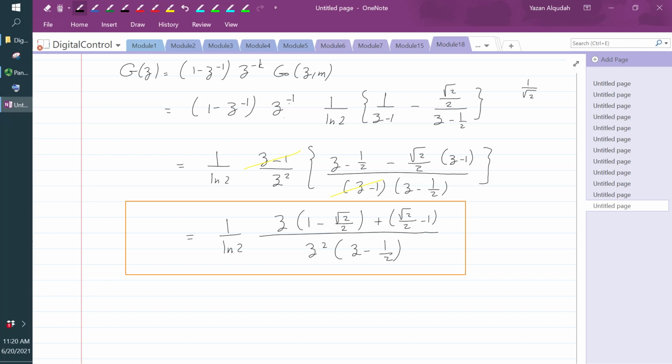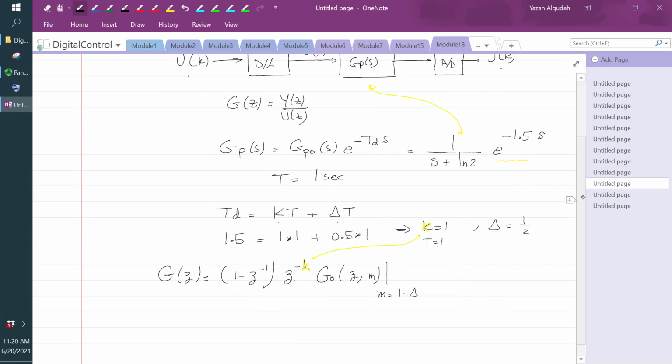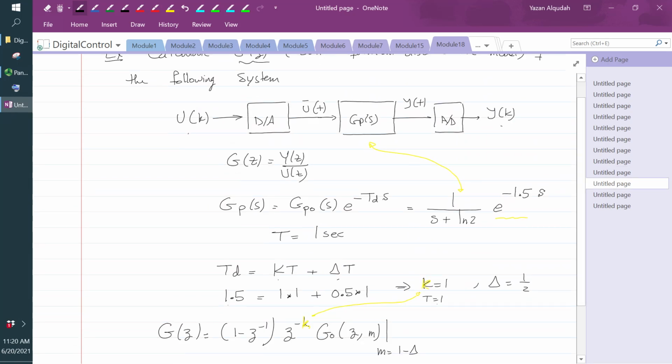Okay, now one thing that I want to mention here before I wrap up is that this shows you the advantage of the digital controller versus the continuous control. If this system, the system that we considered in this example, has a delay, and I were to study this in the continuous time domain, then this delay will result in an infinite number of poles of the system.